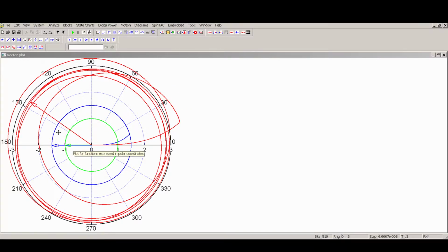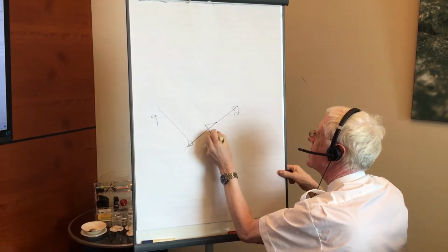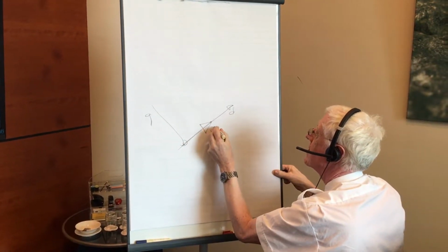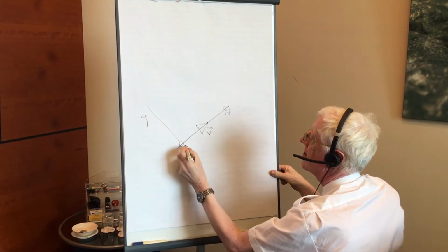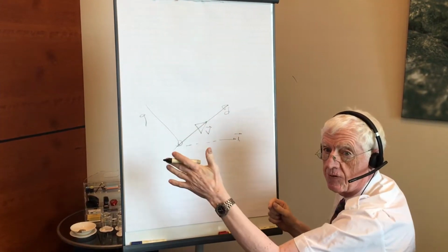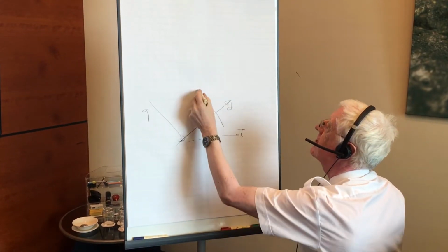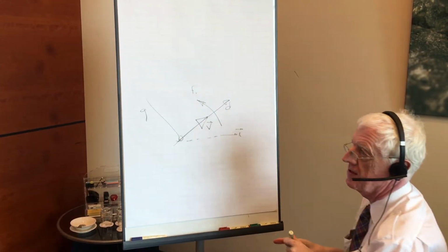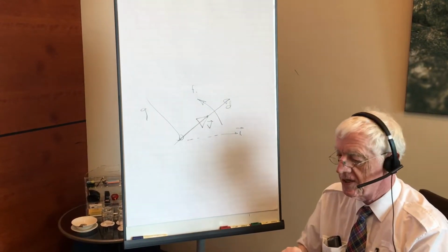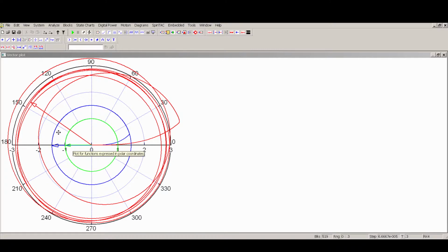Recall that what we did in this case, we have a d-axis and we have a q-axis, and we've set the voltage vector in that direction. This is the v vector in that direction. And the current is the response to it. It's up here. It's down there. So that's what we're basically trying to control here. This rotating vector is set by the frequency which we set. This is the most simple control we can achieve.